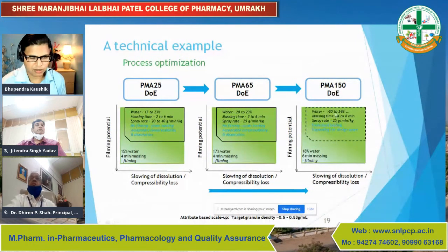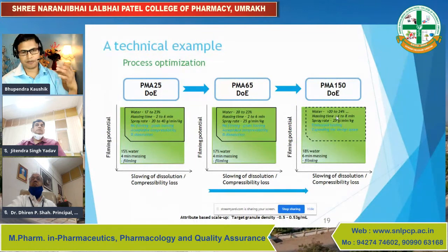So your variability can also come from equipment, the size you're manufacturing, and obviously the age of the equipment itself, because the same equipment was performing slightly differently 10 years ago when it was new. After 10 years, performance may change. So you may have to adapt your strategy. You may have to generate more data and do more experiments to come up with a sweet spot, or an area, where you have more confidence that every time we manufacture within that space, whatever we produce will have the desired effect.